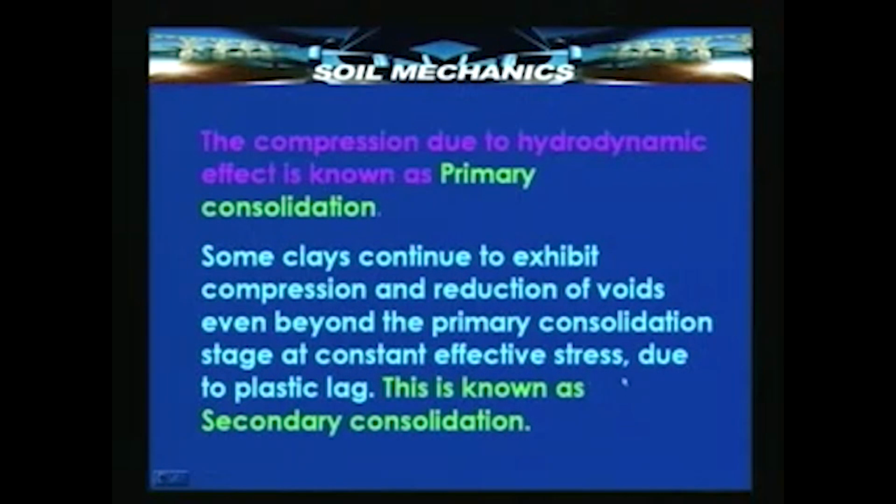So, the compression that we had discussed in very great detail all this time is known as the primary consolidation, and it is due to hydrodynamic lag. And the compression that takes place beyond the primary at constant effective stress due to plastic lag is known as the secondary consolidation.